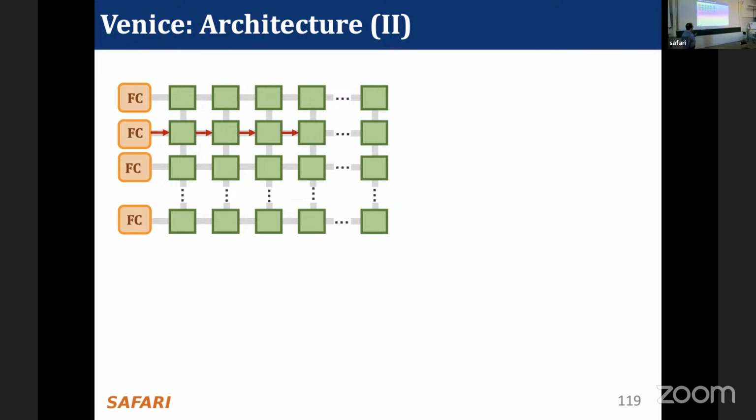From this point, we do a routing function for that scout packet toward the destination. There are some links that, if you take them, you're going to be on the minimal path. There are also some links that, if you take them, you're going to be on a non-minimal path. So we always try to prioritize minimal paths over non-minimal paths. But unfortunately, sometimes minimal paths are not available.